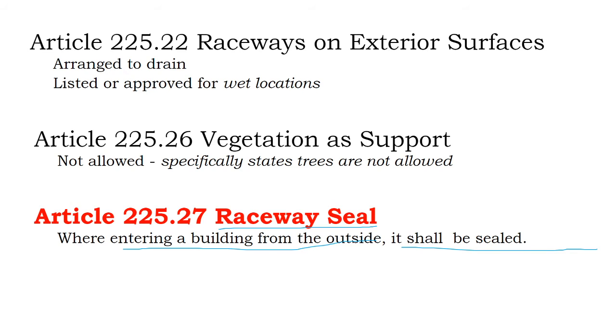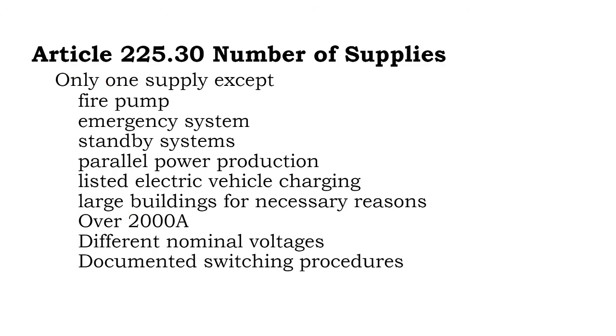But at bare minimum, you need to seal up these conduits because the condensation from air in the conduit itself can cause it to rain inside your conduit. And so a common electrician's exam question is, if you're going from a refrigerated room to a non-refrigerated room, no matter what it is, that's a sealing question. The conduit needs to be sealed because we're talking about two different temperature differentials. That's from the attic to the roof, from underground to inside the house, from outside the house to inside the house, from a refrigerated room to a non-refrigerated room. You need to seal the conduit.